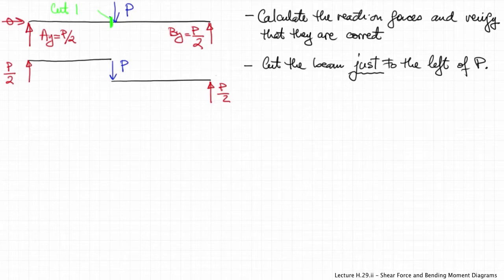So these are the external forces, the reaction forces. Now I'm going to draw the internal forces, and when I do so, I will guess their direction, but it's good practice just to show them with their positive directions, because if your result is negative, that will be the actual sign of that internal force. I'm only showing the shear force and the bending moment.